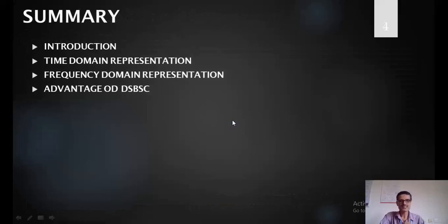But we are going to add some security for information, because the carrier is not available, and by using simple ordinary receivers, it is not possible to tune to your signal. So this is the major advantage of double sideband suppressed carrier modulation of amplitude modulation.